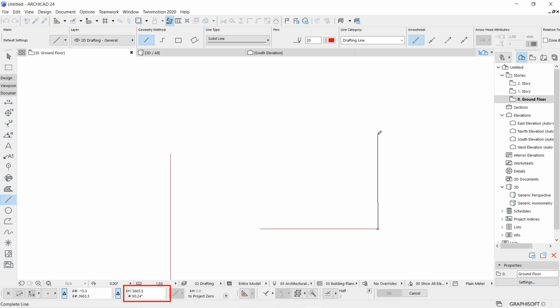So here what I'm going to do is drag my mouse vertically just to get an idea in which degree or direction I'm traveling. Actually from the pick point I'm traveling upward, maybe I'd call that the north side or 12 o'clock. Okay, so that's what I'm trying to do. So in terms of polar, it is 90 degree. So over here, I'm going to press R again from the keyboard, 5000 as my distance, and then press A from the keyboard, 90, and then hit enter.